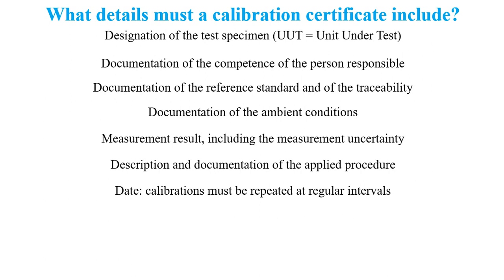Because what happens is, let's assume that you are measuring carbon monoxide emissions from vehicle exhaust tailpipes. The sensor loses preciseness, loses performance as time goes on. So you need to calibrate it time and time again, until your sensor is no longer capable of performing some measurements.